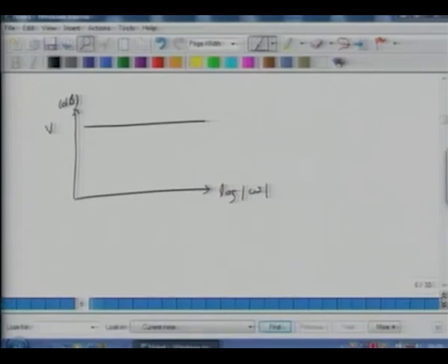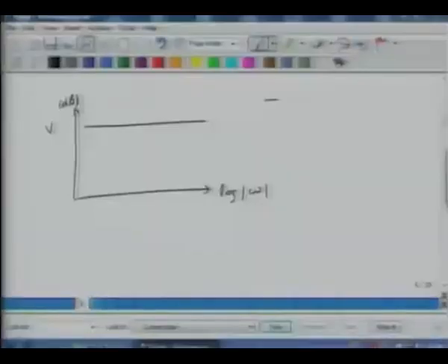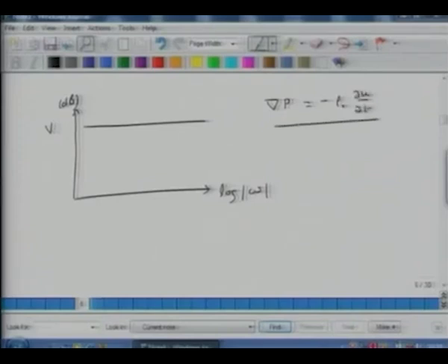So this is how pressure gradient microphones work. They are also called velocity microphones because we know from Newton's law that this is the relation, right? So they are also measuring basically velocity, especially after you have done the integration. That's why they are called velocity microphones. But in the truest sense, they measure pressure gradient.